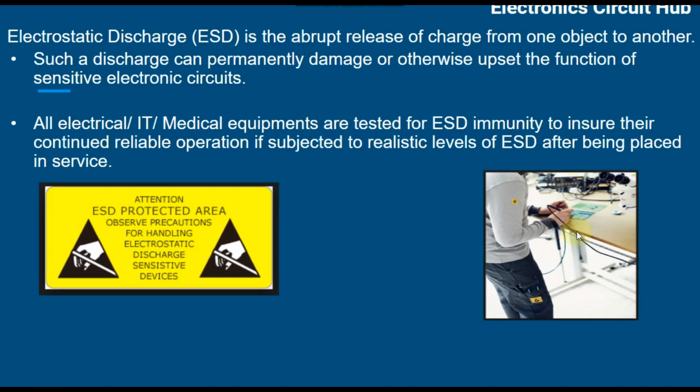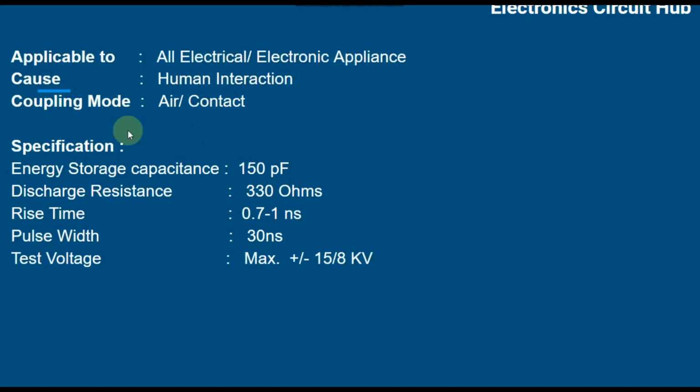One end of this wristband is connected with his hand, and the other end is connected with the earth. That is how you can ensure your floor has ESD protection, right? If you don't wear this wristband, some IC, some components or some board may get damaged due to ESD, right? So let us move ahead.